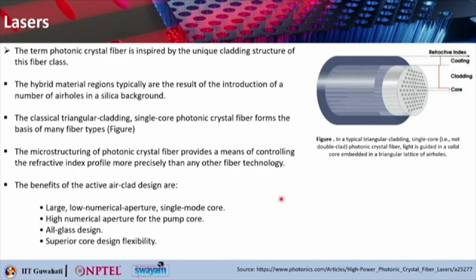So, what are the benefits of this active air clad design? You can actually have a large low numerical aperture single mode core. You can also go for high numerical aperture for the pump core, an all glass design, and then you can have superior core design flexibility. All these things are possible in this particular case.